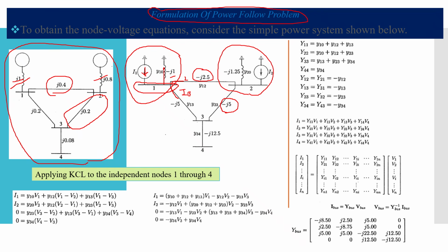So when we take the admittance, we can specify current as a multiplication of voltage with admittance, because if it's impedance, current is obtained as voltage over impedance, but if we convert all parameters to the admittance, we can represent a current as the multiplication of voltage with admittance. So applying a KCL at bus 1, we can obtain this equation. For example, I1 is input current, which is equal to Y10, meaning the admittance from bus 1 to ground, multiplied by voltage 1.